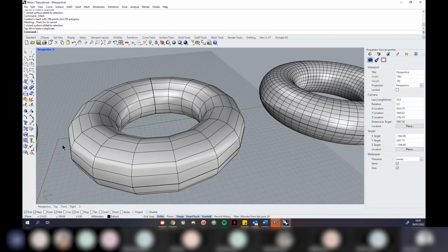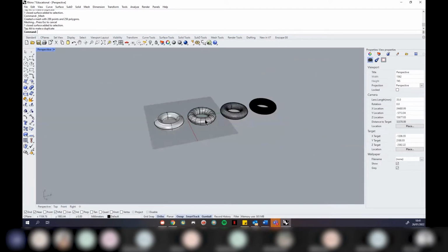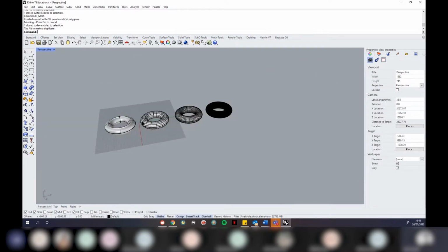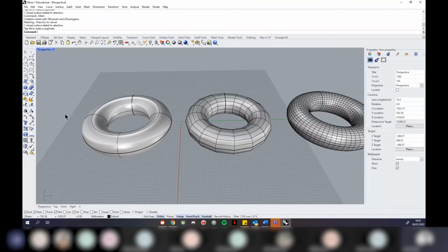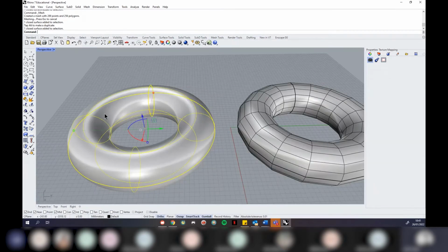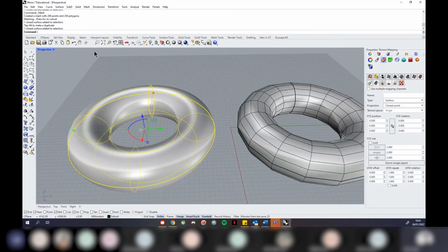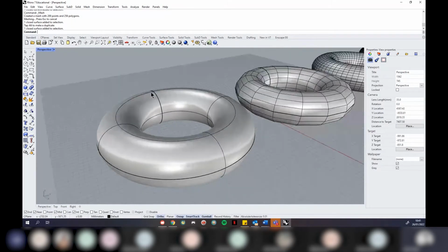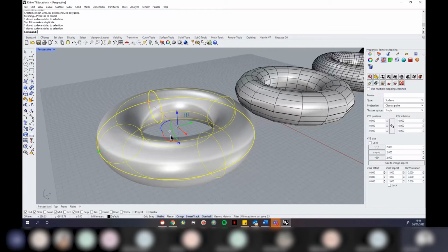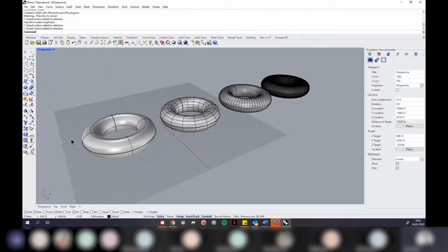So again, just something to think about when you're exporting your meshes. Now, there are benefits of using both. So for instance, if you're making relatively simple objects, chances are you're going to want to use the curve, surface, and solid tools, because this is going to give you nice, clean, light geometry. But as soon as you start cutting into this and making this more complex, it has to basically try and calculate each time how it's going to build the object from X amount of curves. So that can actually start slowing the file down if you make really complex NURBS geometry.